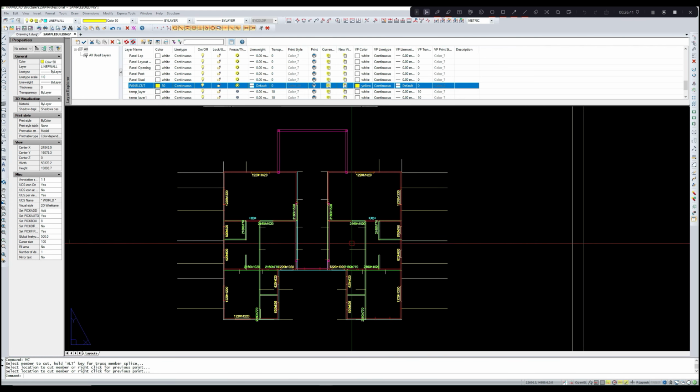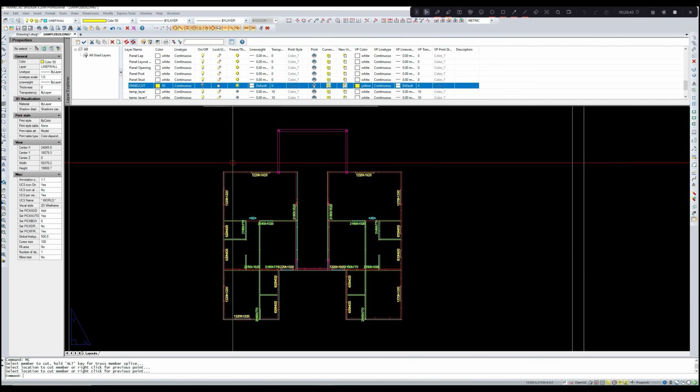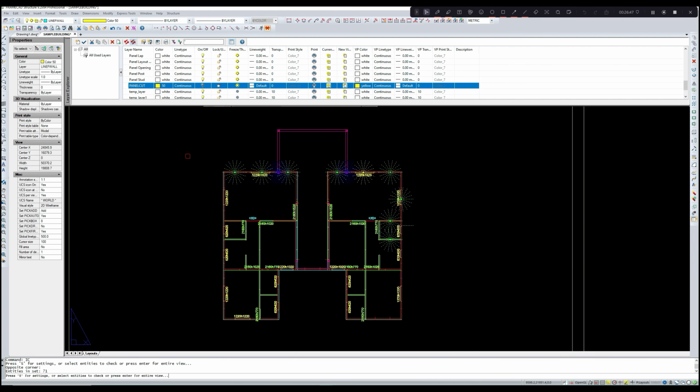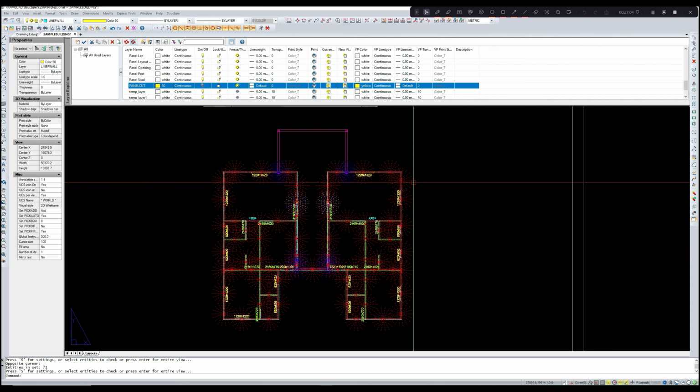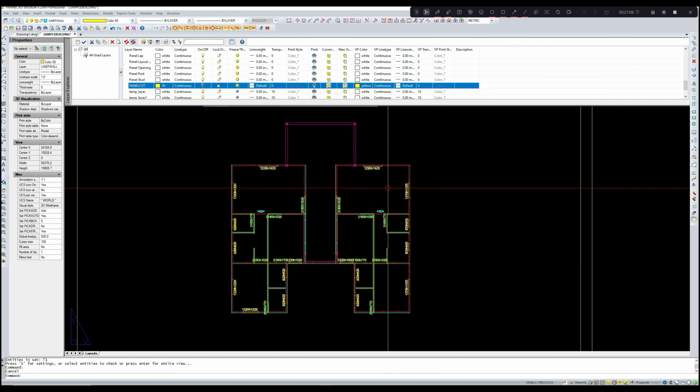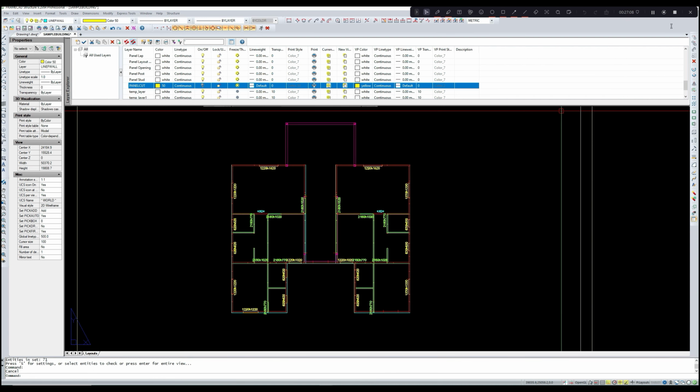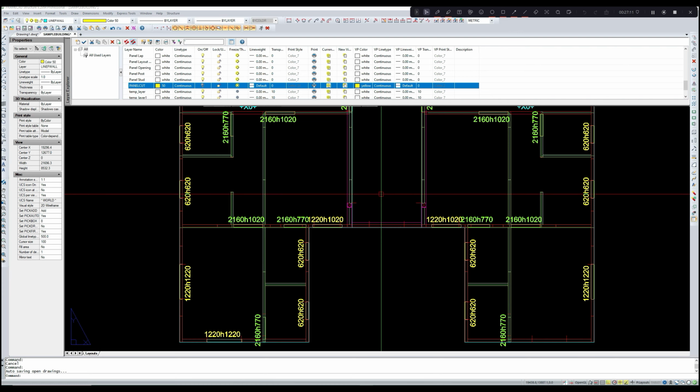So again put off the panel cut layer. Integrity check command. So there is no wall that has been found with panel cuts exceeding maximum length. Now we have to set the wall at the landing level.